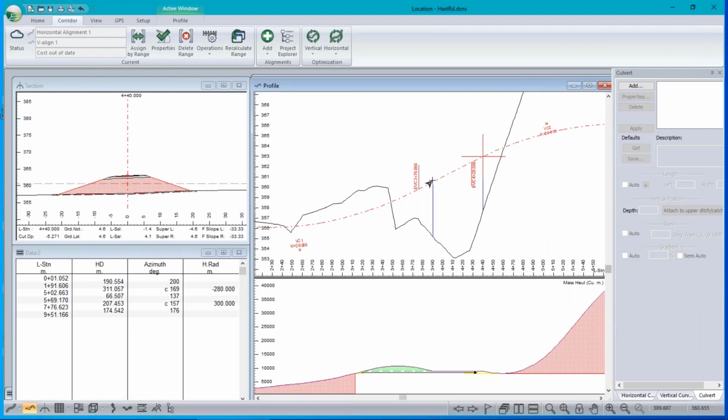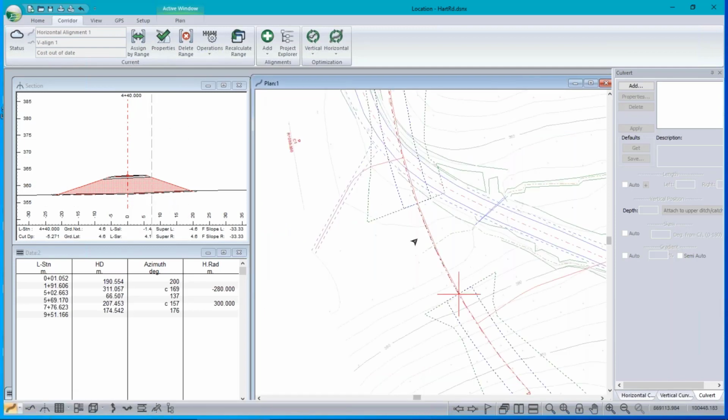If you wanted to make the abutment have a slope in the profile view, or if you wanted to accommodate, say, a wing wall supporting the fill on the back side of the ends of the bridge abutments, then you would need to get out of location module and go into our terrain module. It's beyond the scope of cross-section templates.